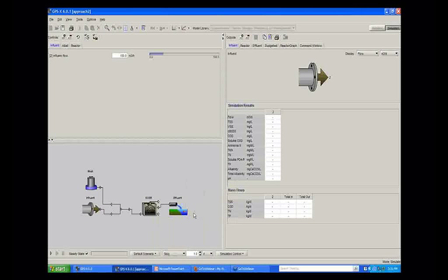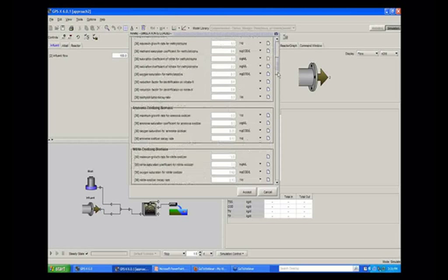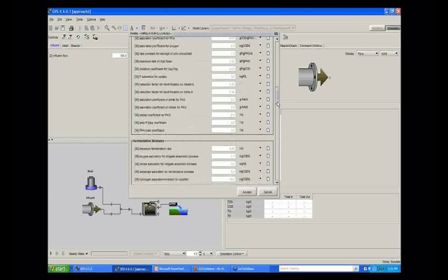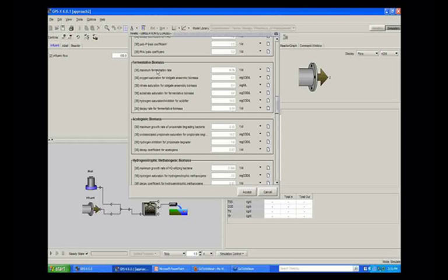and just for the previous question, actually we have the absorption of colloidal COD here in this particular model. And to come back to the question of hydrogen, we have hydrogen producing biomass in the fermentative stage, where we produce hydrogen, and the hydrogen then can be combined with CO2, and there are hydrogenotrophic methanogenic biomass which use the hydrogen and produce methane.